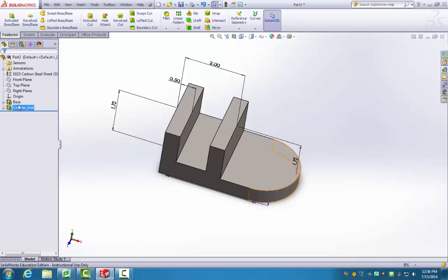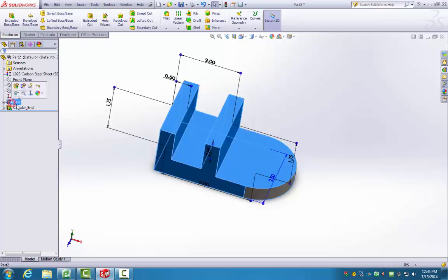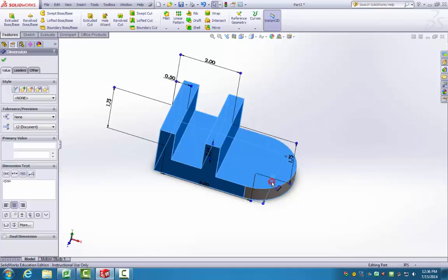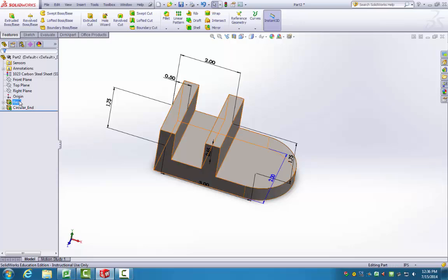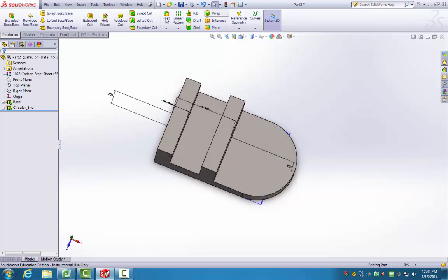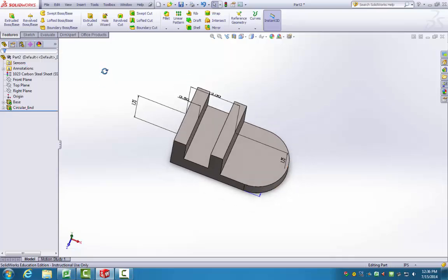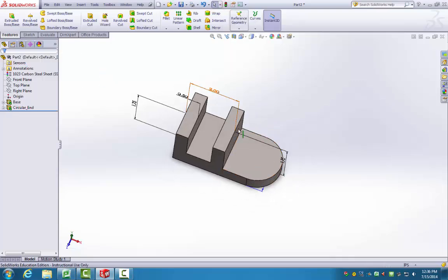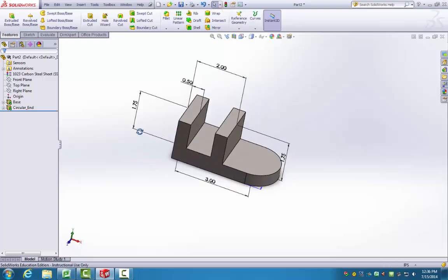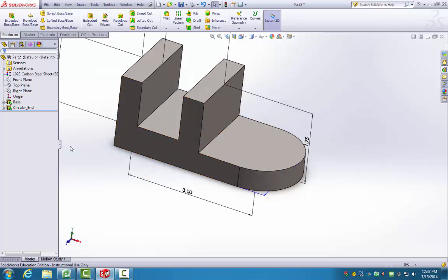The book says on your own, we're now going to change how far it was extruded. So again, we're going to select this, and we're going to go to this 250, and we're just going to make it 2 inches. And again, check. Just to be sure, I don't see the rebuild sign, but I'm just going to rebuild, and now there you go. So even though that rebuild sign wasn't there, it still needed to be rebuilt. Whenever you do some modifications to things you've done in the past, it's always safe to hit rebuild before you carry on, just to make sure they were done correctly.